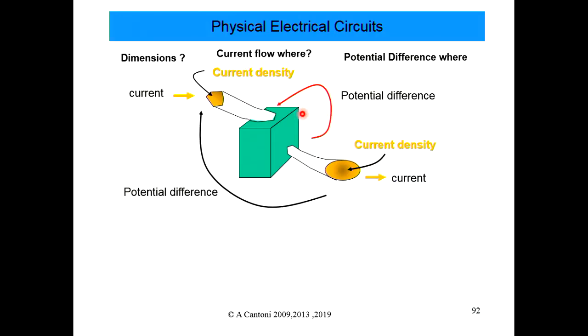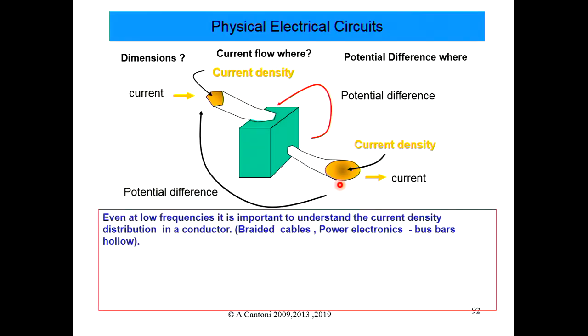So if you measure the potential difference at the terminals or at the ends of wires that connect to the terminals of components, they'll actually look a bit different. So it's important to understand the limitations of the components you're using and the frequency you're interested in, and how well the model approximates the real device. Typically, if you've got appropriate leads for the frequency and they're good conductors, you can assume it's effectively a lossless wire with zero delay.